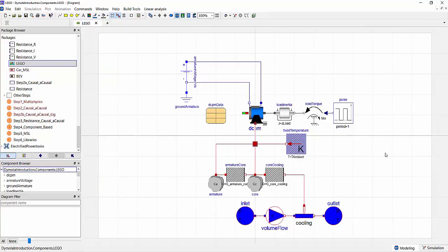We see a lot of components in here that are very generic and can be used in lots of different simulation models. This also talks to the overall object-oriented nature of Modelica, where we can use all the concepts from object-oriented programming and modeling that we've come to know and love, such as inheritance, encapsulation, abstraction, and many more.